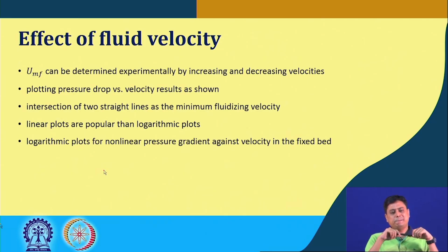So, typically linear plots are more popular than logarithmic plots, but logarithmic plots become unavoidable when there is a non-linear pressure gradient against velocity in the fixed bed. When the flow regime shifts from laminar to the transition or turbulent region, the pressure drop does not vary linearly with the superficial velocity.